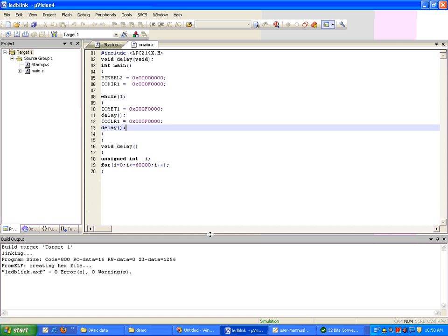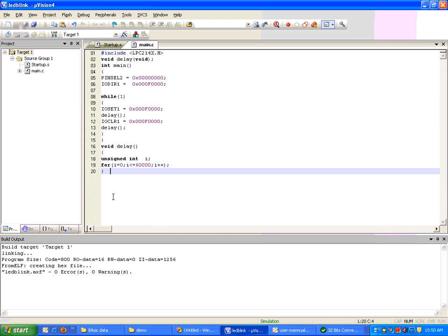We will see how all the LEDs and registers are set high or low. Now I need to debug this function. Compilation is over, and now I want to debug to check whether it executes correctly or not. I want to see it in the simulation part only. This is called simulation. If you see the output on the board, that is called emulation. In the ARM architecture we have in-circuit emulation, which means we can see the execution in the hardware part, and in the simulation part also.